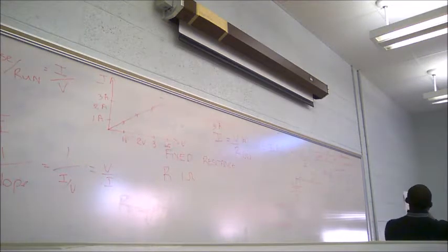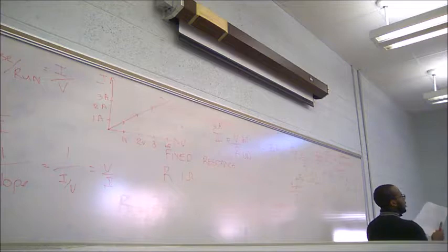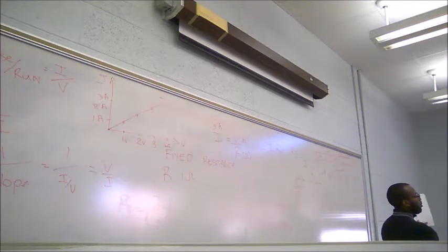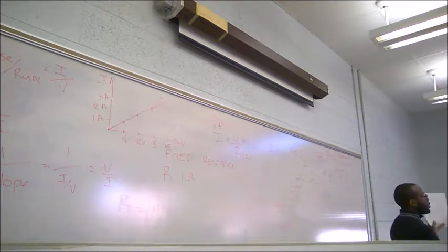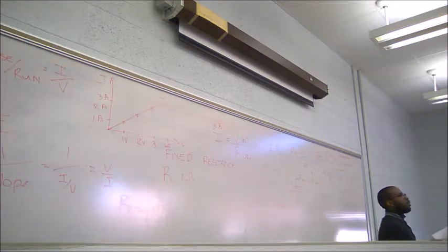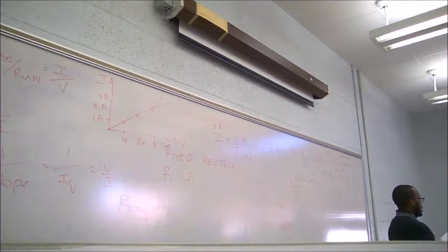You have the nominal resistance here, and based on the resistor you have, you need to find out what the tolerance is, whether it's gold, 5% or 2%. Then you also need to calculate the maximum and minimum resistance, and then you will take your meter and measure the resistance of the resistor. If it falls within the range, you check the box. Super easy.